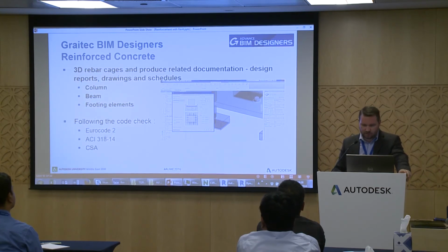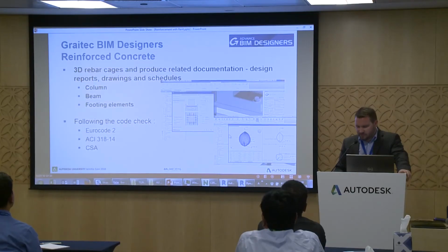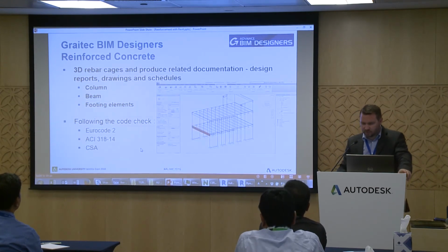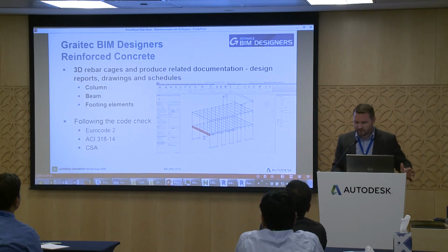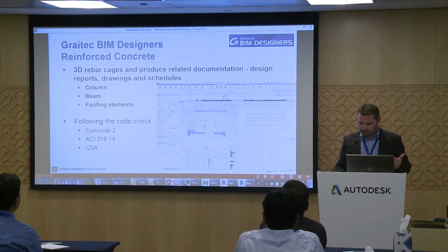So here you will do the reinforcement and the code check directly. Okay, you don't have to go to Advanced Design, come back, etc. And you can have directly, in the Revit environment, all the results you need and the calculation notes. You can select one or multiple elements, send them to this extension, have all the results you need, and come back.